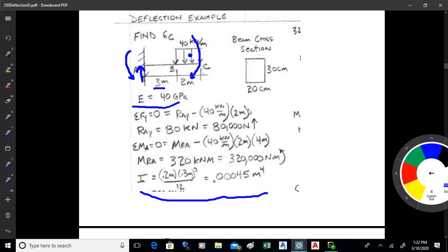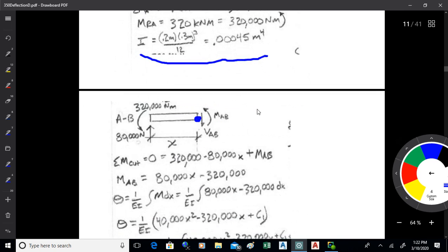So when we get the moments, we want to convert them into inch pounds immediately, okay? Especially when you're doing English problems, don't try to mix pound feet with inch dimensions. It just turns into a mess. So get everything into pounds and inches if you're in English. Everything into newtons and meters if you're doing metric, okay?